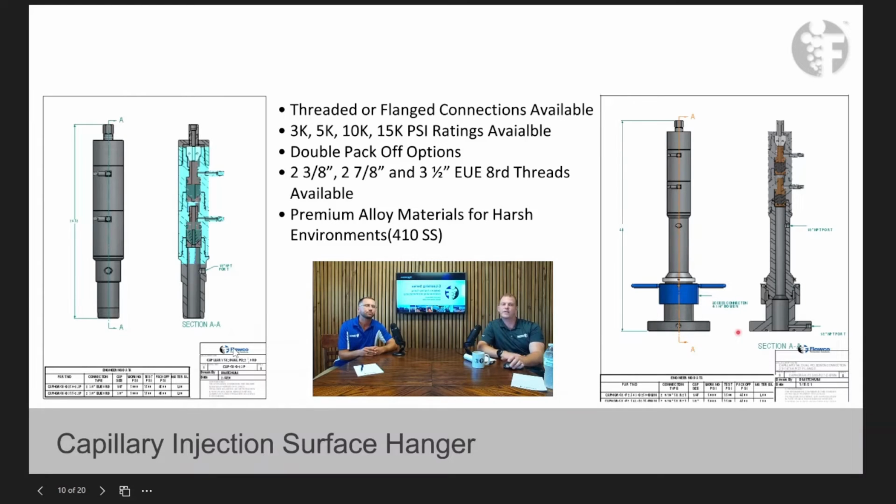Okay, well, that's good to know, because sometimes if you have a blowout condition or well control, you may need to shut that master valve to close that well. And a lot of times they won't fall very far if you have an emergency situation and have to cut the line. Usually it falls maybe 50 feet, something like that, because you have to remember that string has memory in it.